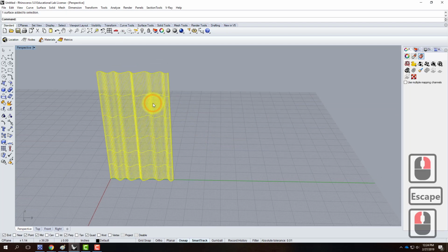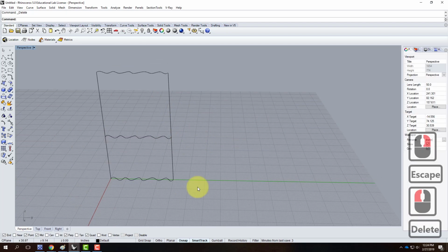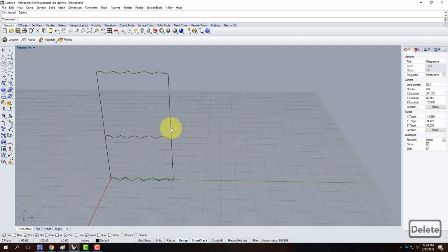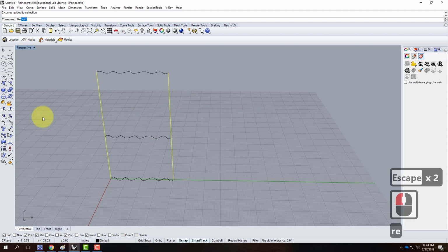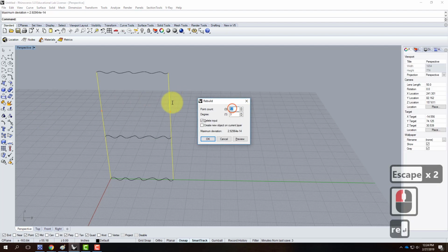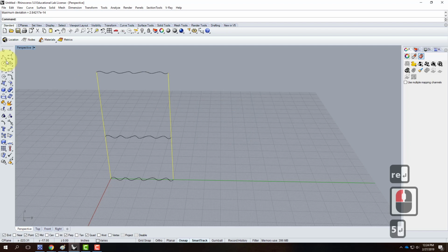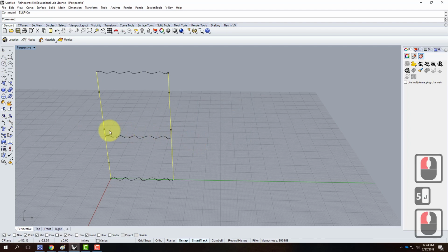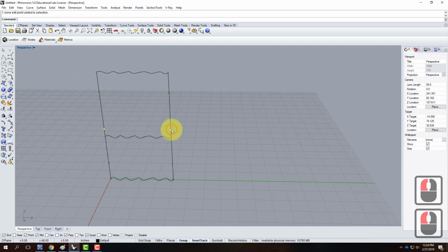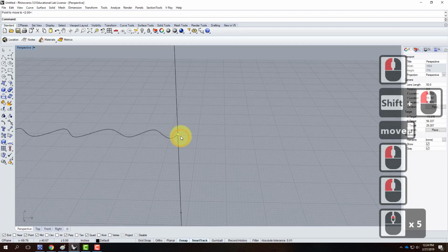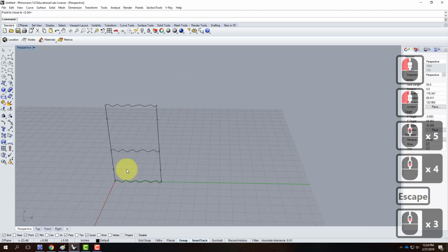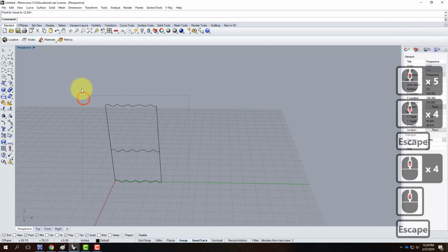What happens if I want it to sway or bow? I can do the same kinds of things. This time, I would take these pieces here. I might need to rebuild these two curves first. So let me rebuild real quick. And I'm going to do those as 5. Show them here. I'm going to move these 2 points so that they end up right on the ends of this line. Then I can show all the points.